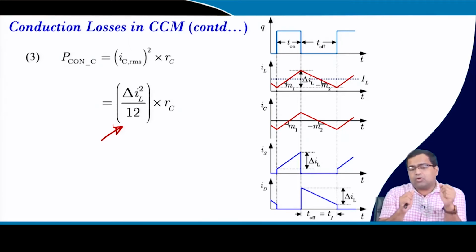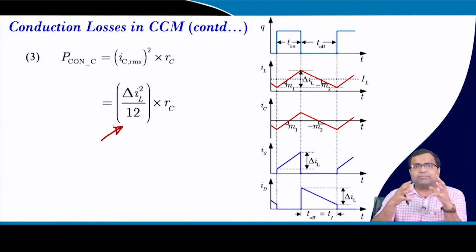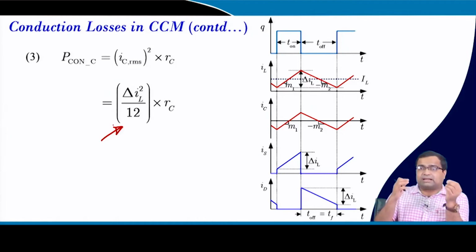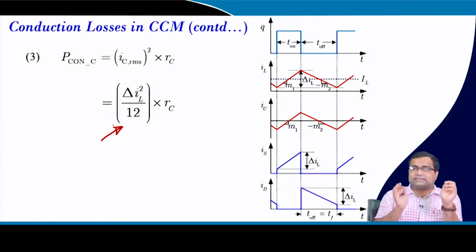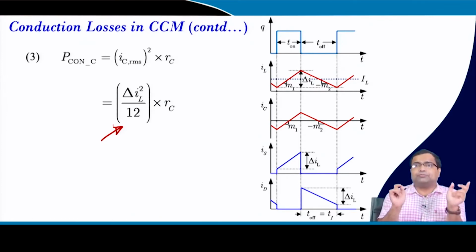Now, consider a very light load condition. If you talk about LED driving, dimmable LED, particularly PWM dimming, then the LED string will be connected and disconnected. Suppose a buck converter is driving an LED; once it is disconnected, the output current of the buck converter is 0.